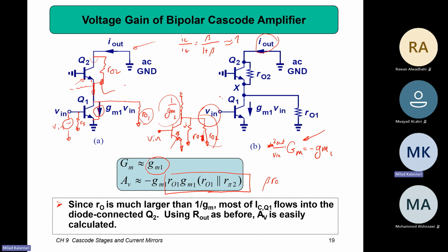This is saying that making a cascode amplifier boosts the gain maybe beta times compared to the normal common emitter. The gain would be beta times higher. So if we could reach a gain of 100 for the simple common emitter, where beta itself is like 100, just this single stage amplifier with a cascode can make a gain of 10,000. This is then a good tool for the op amp to make the high gain.